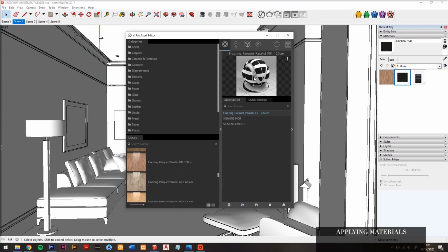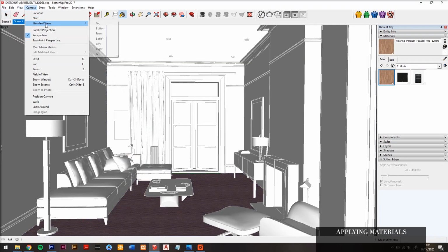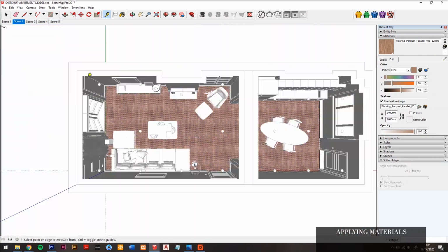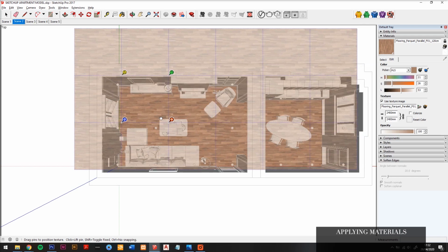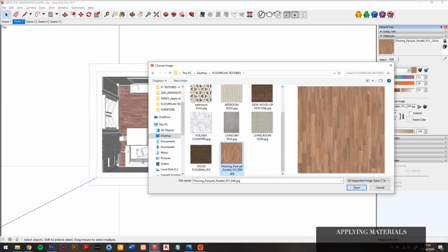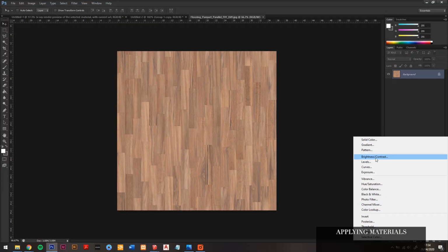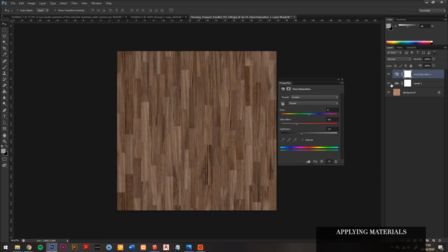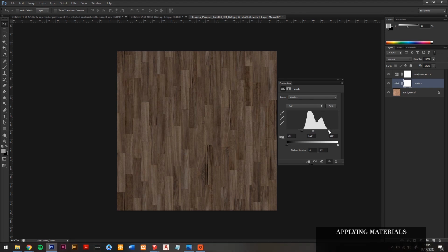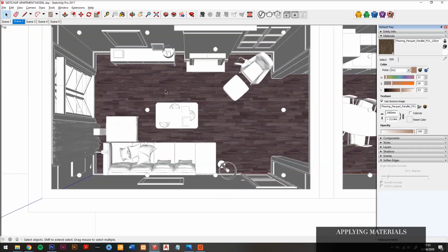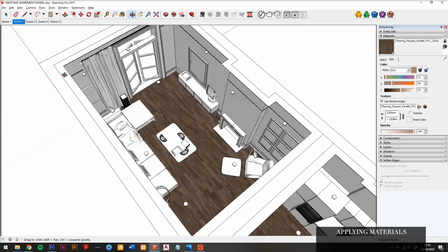Now let's start adding materials for the V-Ray renders. So floorboards, most important. I always try to check that the scale of the floorboards is correct. You don't want floorboards that look too narrow or too wide, because the render will look wrong straight away. I'm just going to change it based on a sample we have. We have this quite dark hardwood flooring. That looks good. 120 for the width.